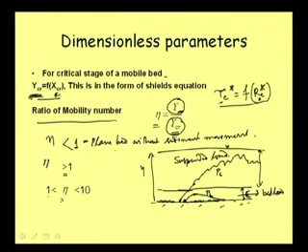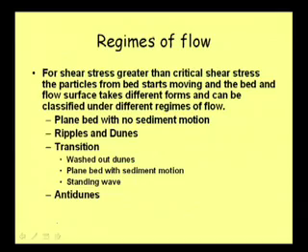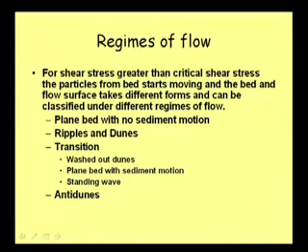Well, with this very basic understanding of suspended load and bed load, now we can talk about regime of flow. So, what we mean by regime of flow is that for shear stress greater than the critical shear stress, the particles from the bed start moving, and the bed and the flow surface take different forms.